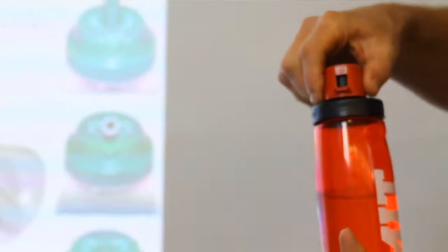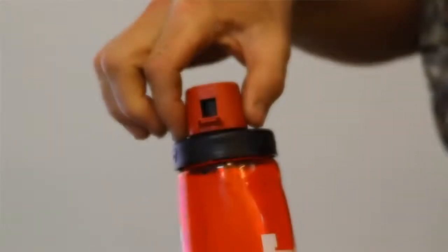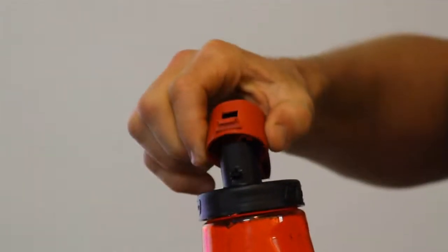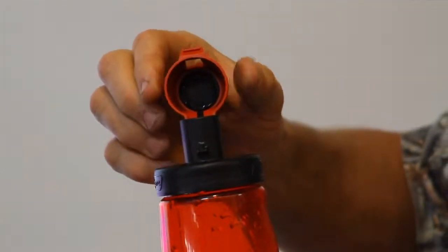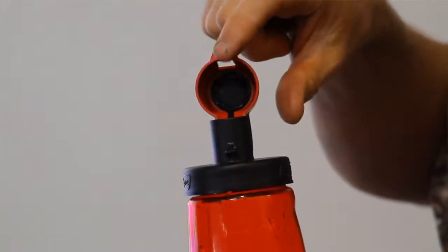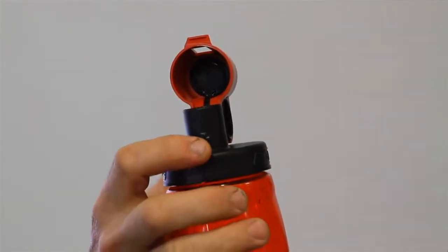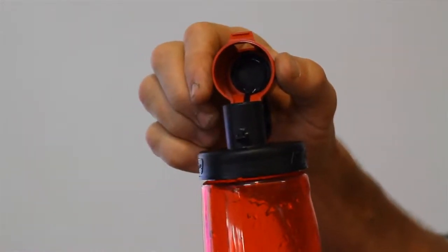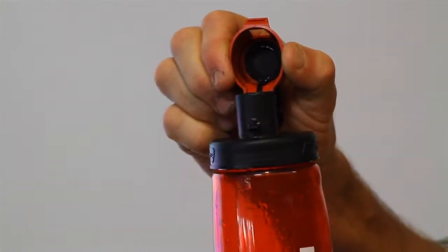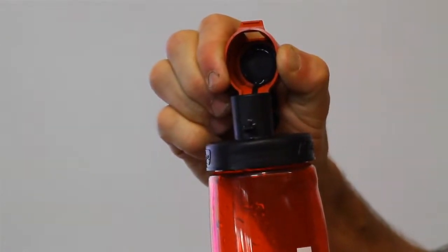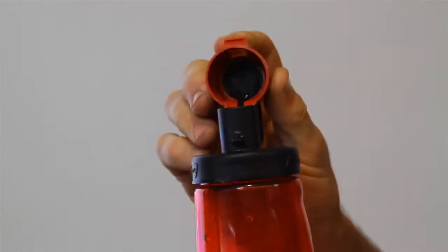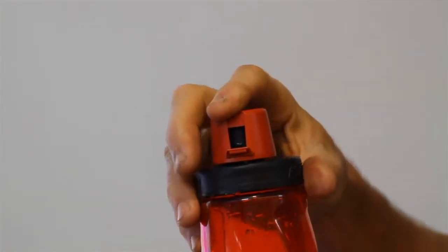Well, if you look at it closely here, watch what happens when I squeeze. Maybe it's very subtle, but maybe look here even a little closer. It's round, and this lip is catching on this tang sticking out. And when I push here, the round turns oval, and the axis of that ellipse is of a larger diameter than the initial circle. So it snaps shut.